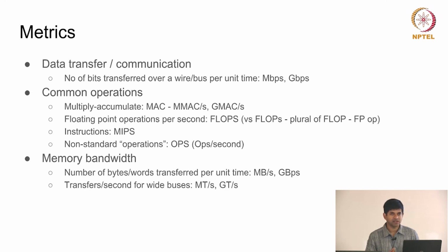Then ultimately that microphone is basically being connected by one wire to your A to D converter, and the A to D converter then has to basically pick up the data, convert it into a digital format, and then transmit it somehow. That transmission could either be over a serial bus or over some kind of a parallel 8-bit wide interface. All of those ultimately translate into number of bits that can be transferred per unit time, okay? The typical units for this are megabits per second, gigabits per second. You could have kilobits per second, but nowadays